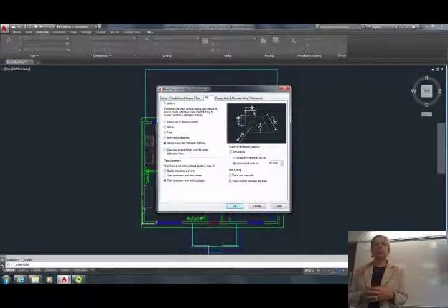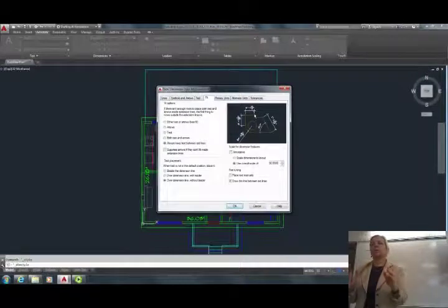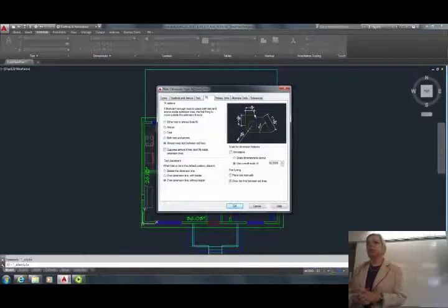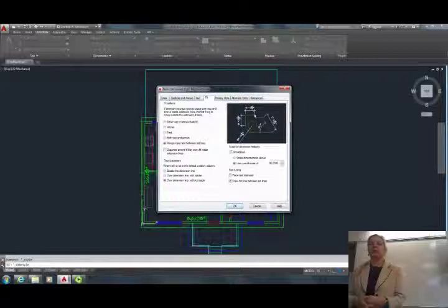On the drawings that I will be looking at, I don't want to see any fractions. Your drawing is going to look horrific. Your floor plan for the whole house is going to be horrific on 8.5 by 11 if you're showing any fractions. Trust me, in 1/8 of an inch scale on a small sheet, no contractor, no designer would care about 1/32 or 1/8 of an inch dimension. But more importantly, you want to have a set of drawings that's going to be smashing, looking beautiful. You want to be able to take it to interview, show it to somebody, and look good.